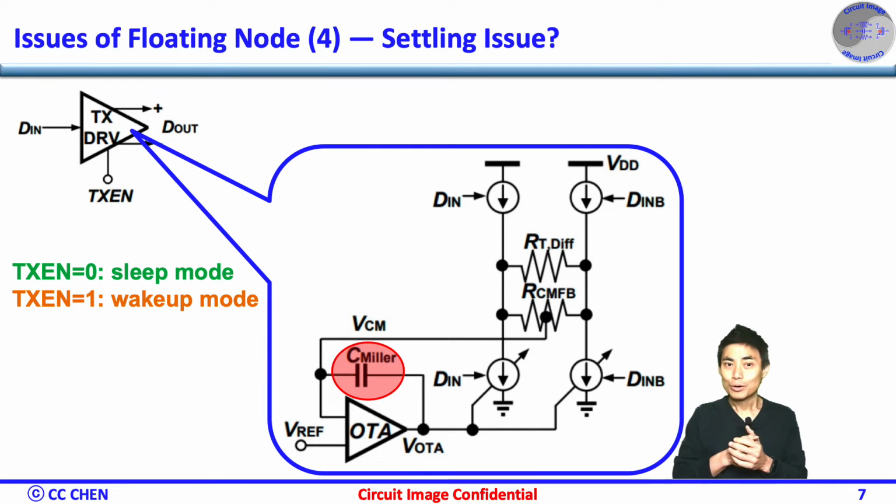On the other hand, when the data is ready to send, the TX driver must wake up as soon as possible. In this simplified H-bridge driver, there's a common mode feedback loop to set the driver's output common mode properly over the PVT.